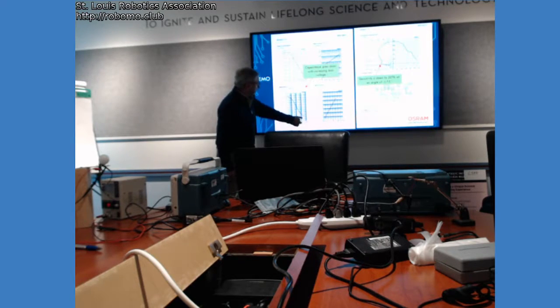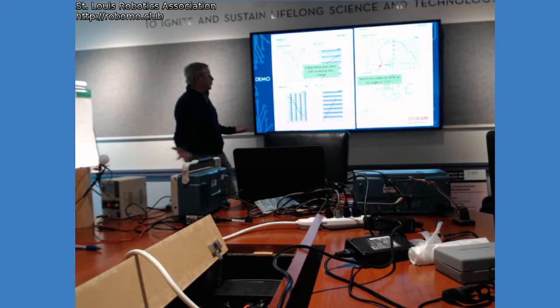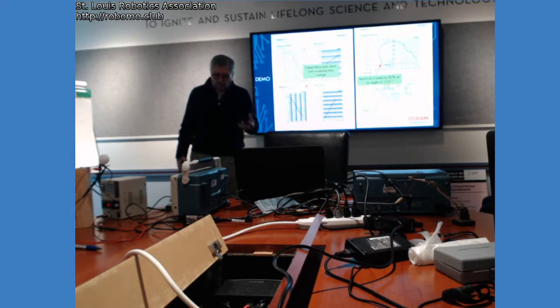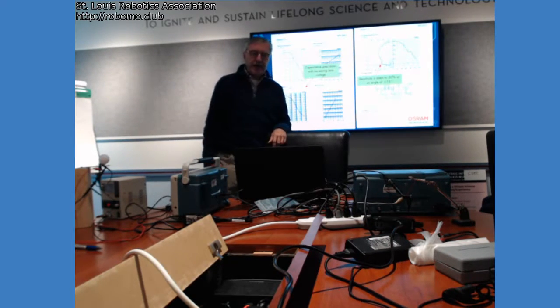And if you take the voltage all the way to 20 volts, you'll have 2 picofarads. So if you're really trying to get high speed out of this, you'd want to think about what reverse bias to use.